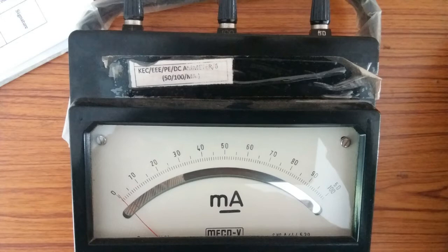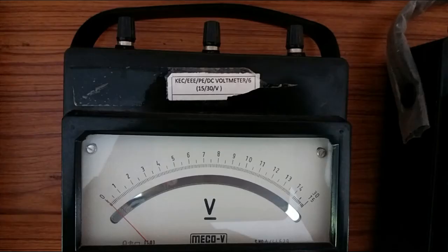It is the moving coil ammeter used to measure gate current. It can be connected between the terminals 0 to 50 milliamps. Since its scale is in 100 milliamps range, the actual value can be calculated from the measured value by dividing by 2. It is the moving coil voltmeter used to measure anode cathode voltage.